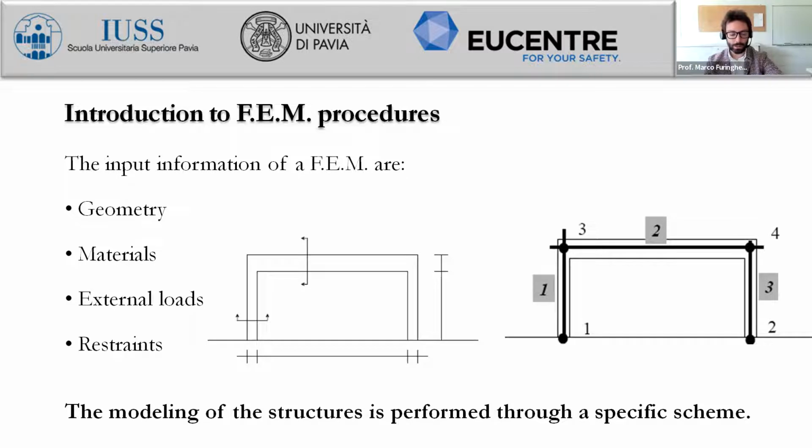Okay, this is very important, because we have to keep in mind that we look at geometry and something geometrical because we look at a three-dimensional model within a software, which is very useful because actually we can see what we are modeling, the actual connection between the elements, and also the frame elements is actually represented by a single line. But even though this is a line, we have to keep in mind that the formulation and the expressions for the finite element, the frame finite element, is just lumped. All the information are lumped within the two nodes.